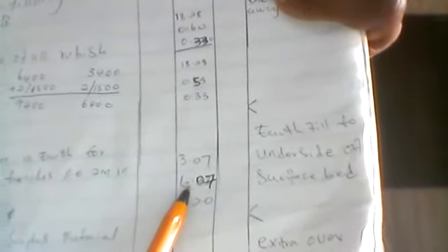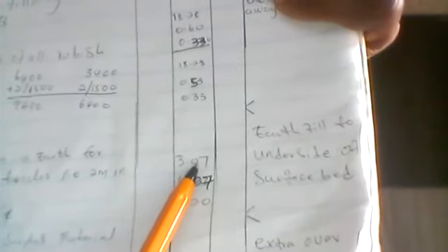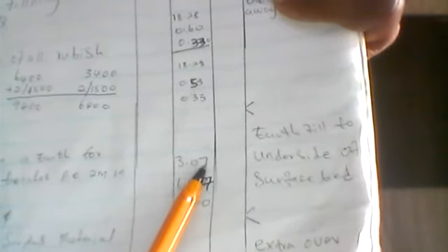So it's 6,400 minus the thickness of the wall, 330, divided by 1,000, which gives you 6.07. It's 3,400 minus 330 divided by 1,000, which is 3.07, and then you multiply it by the 200, the thickness of the earth fill. So now we're done with backfill and earth fill.